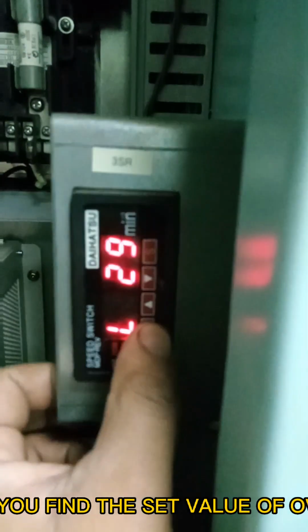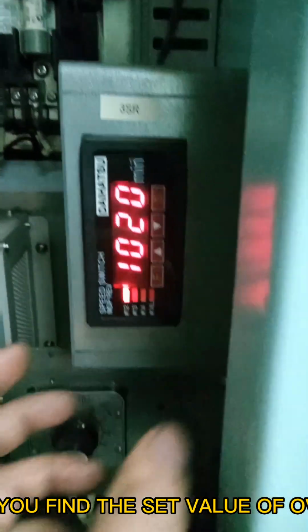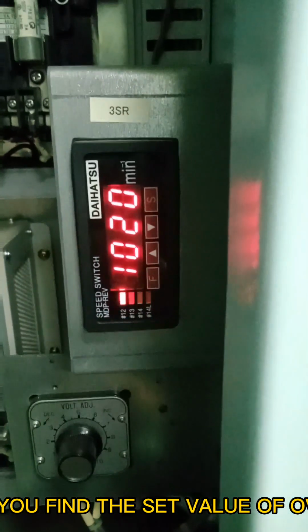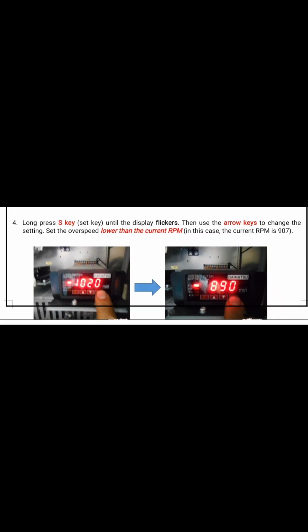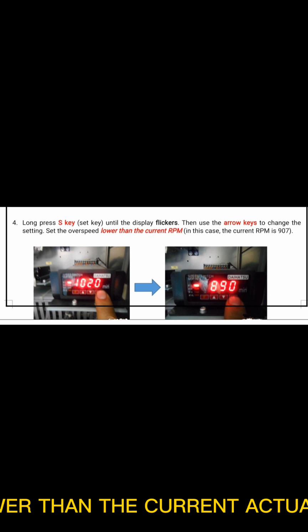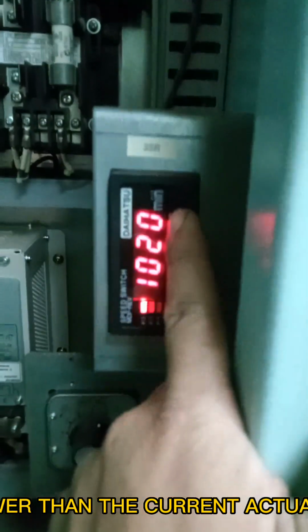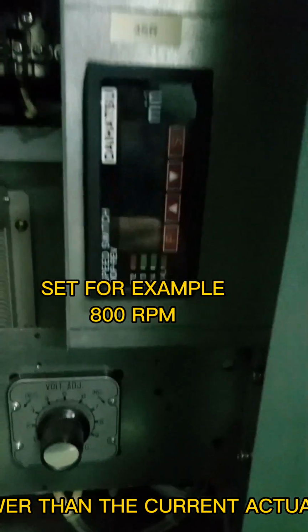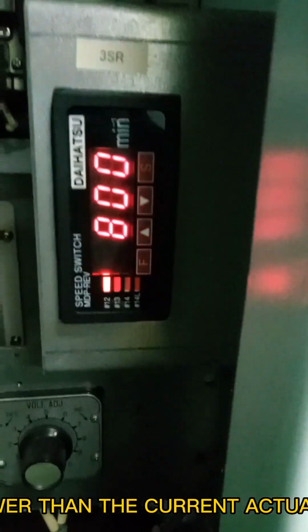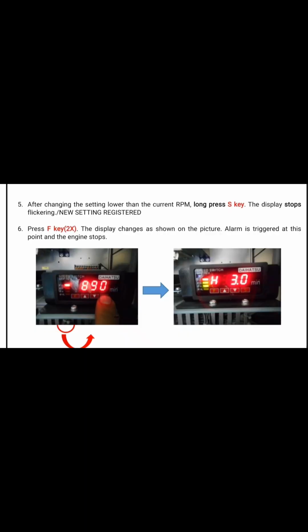Next step, press the F key or function key until you find the set value of the overspeed trip, which usually is 1020 at 900 normal RPM. Next step, long press the S key until the display flickers. If the display flickers, this means you can now change the setting. Now you can decrease the setting using the arrow down key until lower than the current actual RPM. The actual RPM is 900 RPM, so you can decrease lower than that. I set the RPM to 800 RPM.